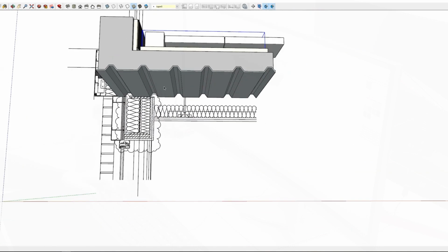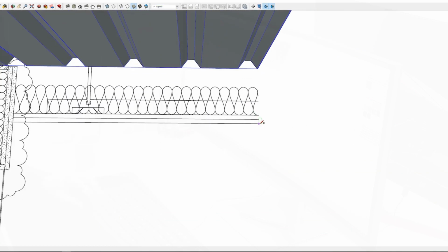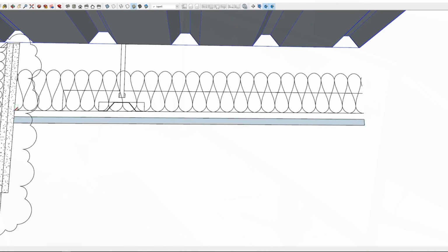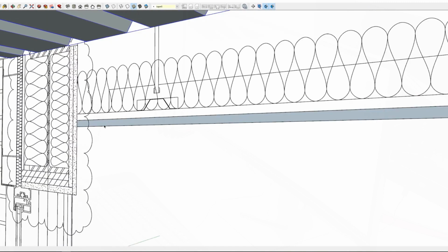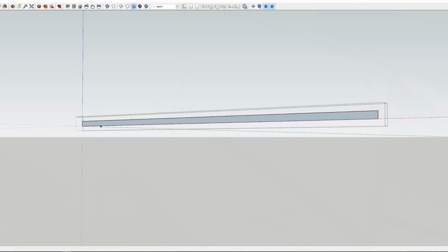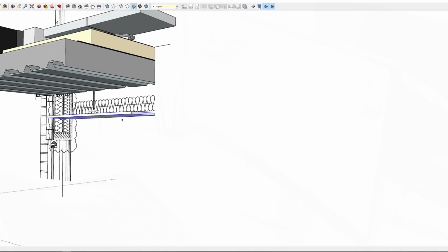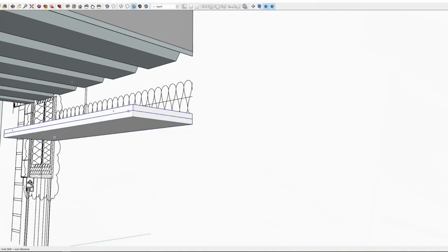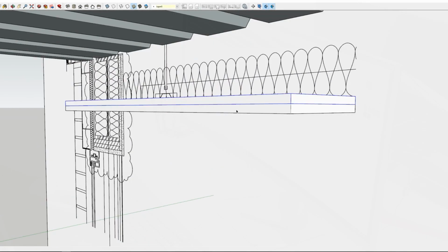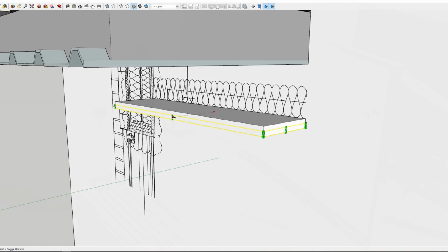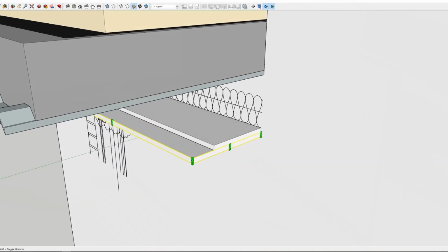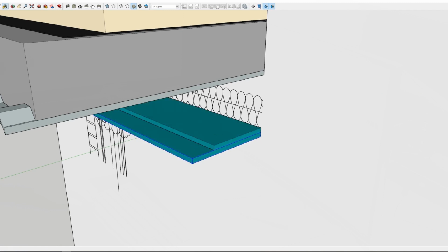Let's work under here because obviously we want to hide all that. So for acoustic reasons, we've got a double boarded ceiling, acoustic rated boards. Acoustic rated plasterboards. They're actually, before the finish, coloured in a blue. Sort of that colour.